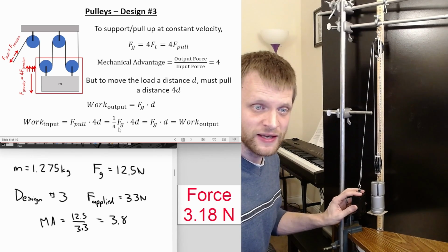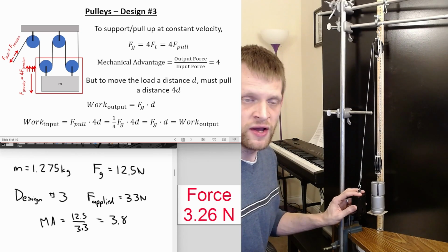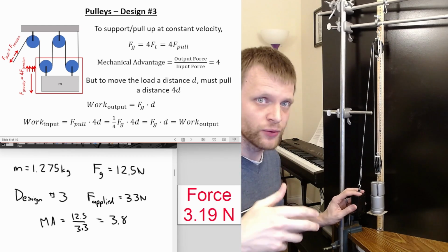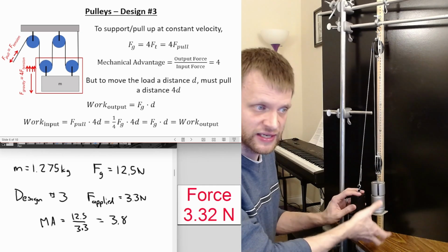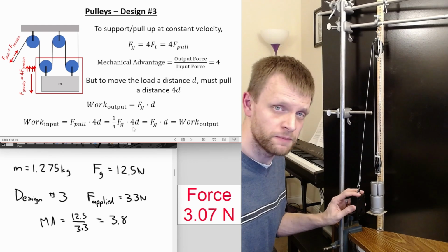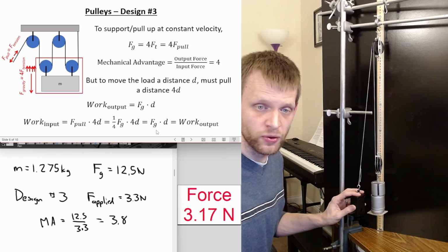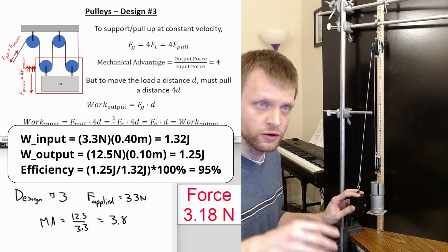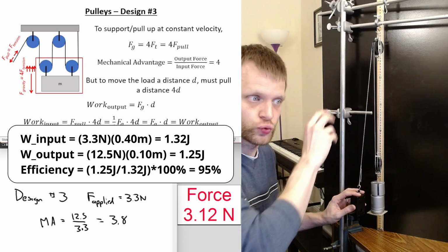And again, if we had the best possible system, the exact theoretical mechanical advantage, then the amount of work, the amount of energy that we have to add to the system will match the amount of work that is output in lifting this object upwards. I'm using only 1/4 of the force, but I have to apply that force over 4 times the distance. The input work and the output work are going to match. And for this actual system, for the actual measurements that we made, I'll throw up a calculation of what is the efficiency of this actual pulley setup.